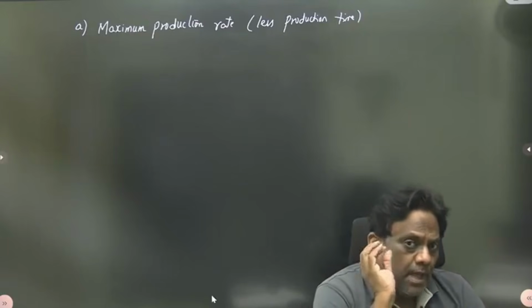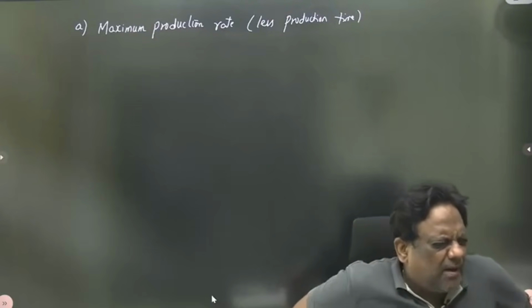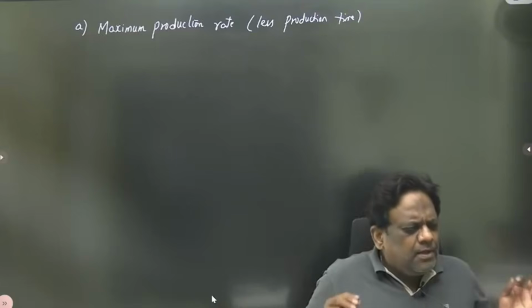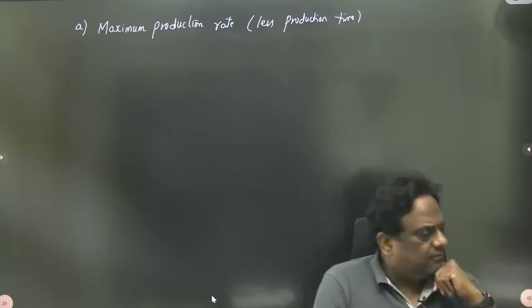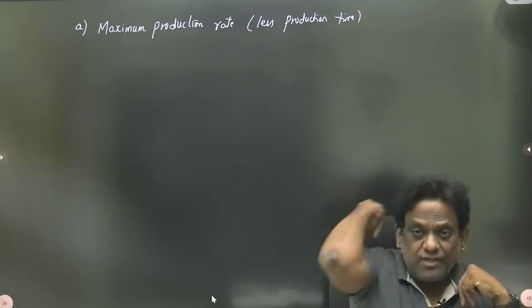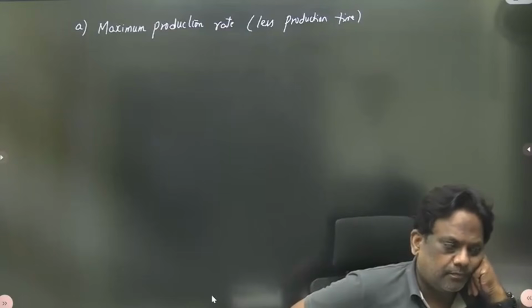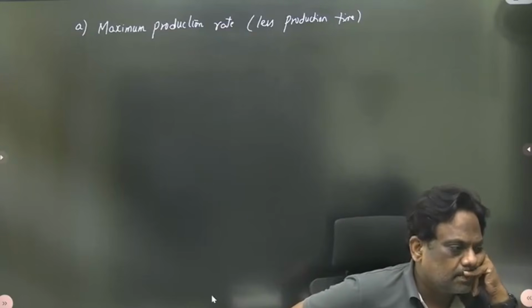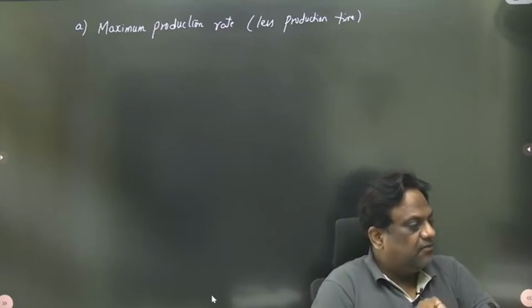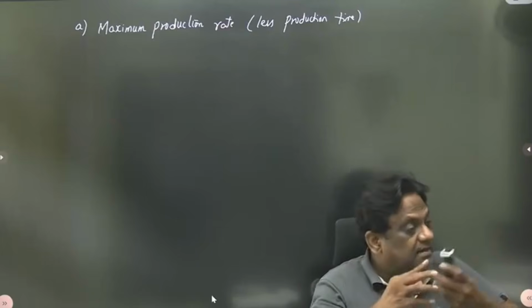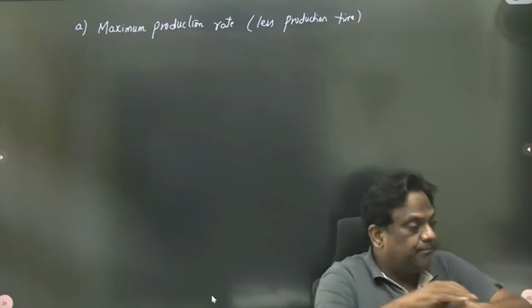Actually, the most important part I have taught you very clearly. Which parameter is playing a vital role on tool life? I repeat, which parameter is playing a vital role on tool life? No one is answering. Velocity, exactly. It is the cutting velocity. The cutting velocity plays a very, very important role.